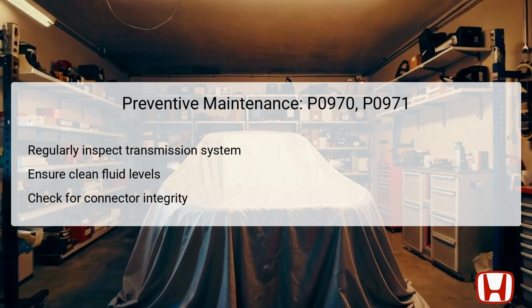Check the integrity of all connectors involved in the transmission control system periodically. Ensuring that these preventive measures are taken will significantly enhance the longevity of the CVT system and its associated components, thus maintaining optimal vehicle performance.